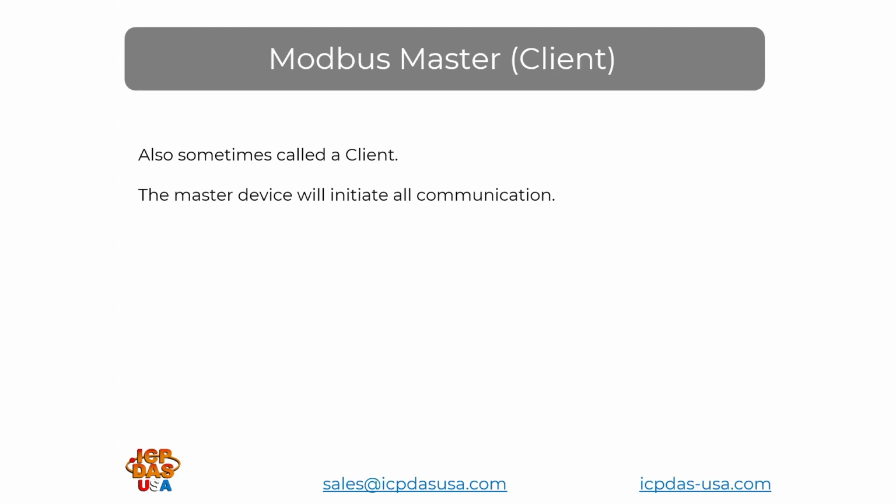The master device is traditionally a PLC, PC, or HMI. It is sometimes called a client in industrial terminology. The master device will always initiate read-write requests for specific data from a specific slave device. The master device will then process the data to perform its desired function, whether it be to run a manufacturing application from a PLC, perform data logging, or control from an HMI.